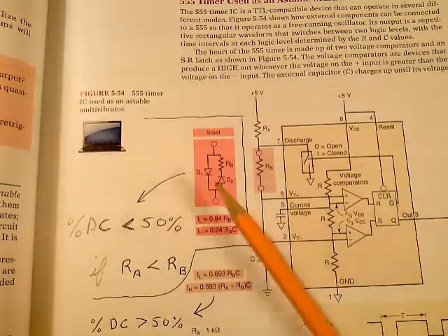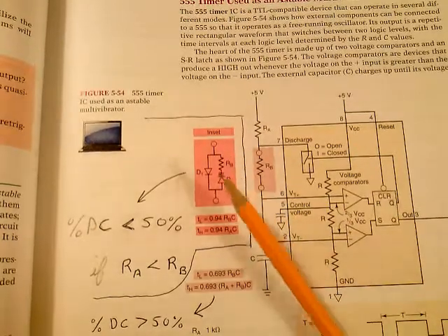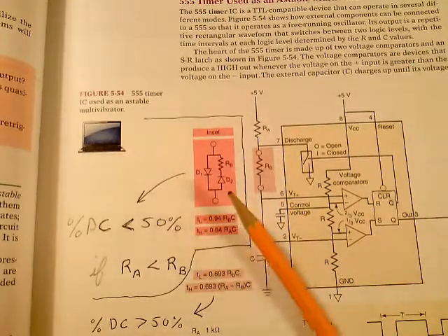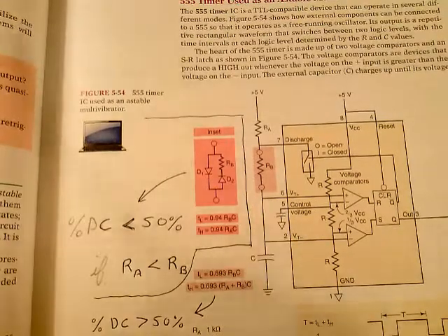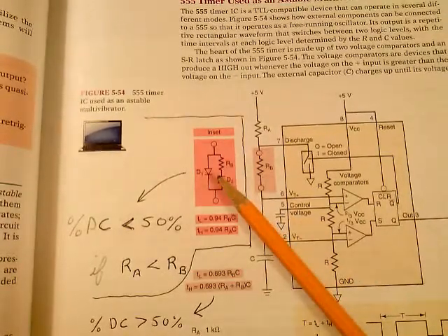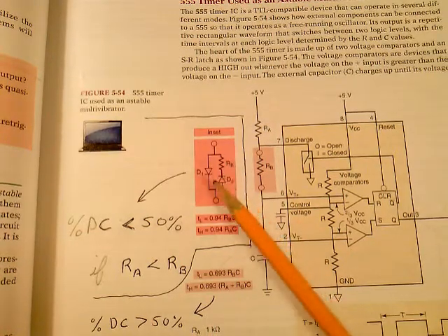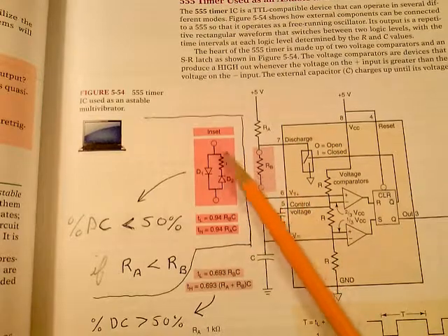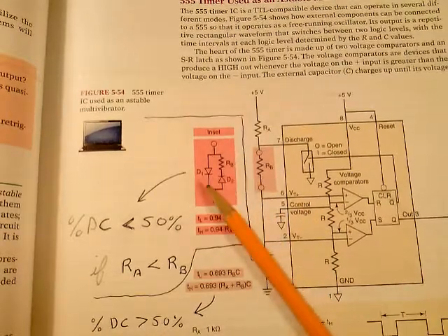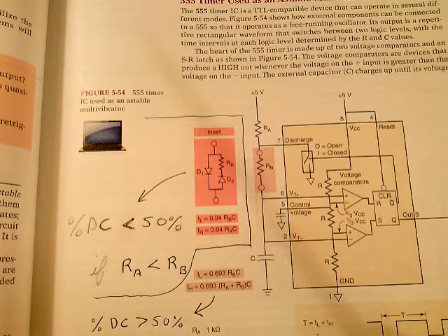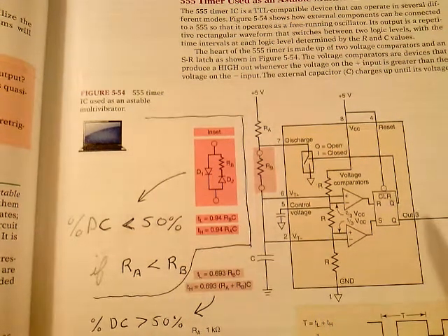Now, in the lab, you can do it that way because you're going to have to build this in the lab. You'll see this in just a minute. But if you need a 20% duty cycle, rather than going through this extra work of replacing that value of RB with this combination here, what I would recommend for our application is to design a circuit for an 80% duty cycle and then use an inverter on the output, out here on the output. Think about that.